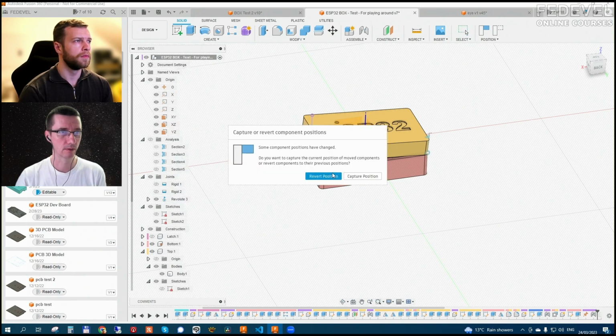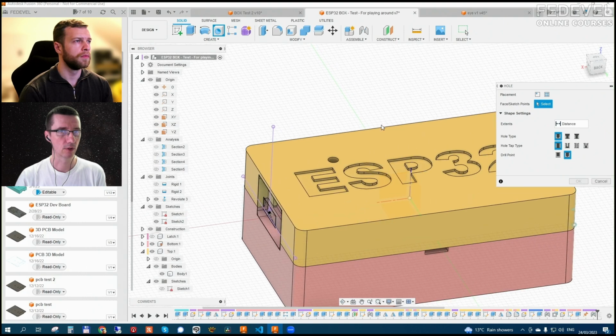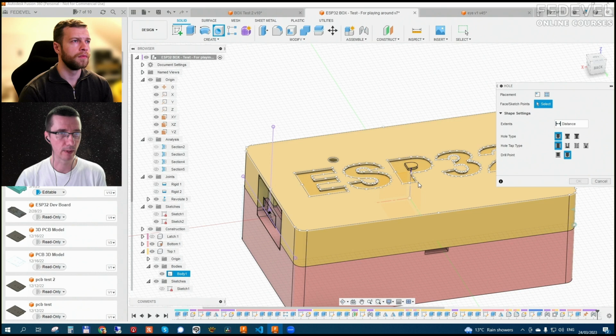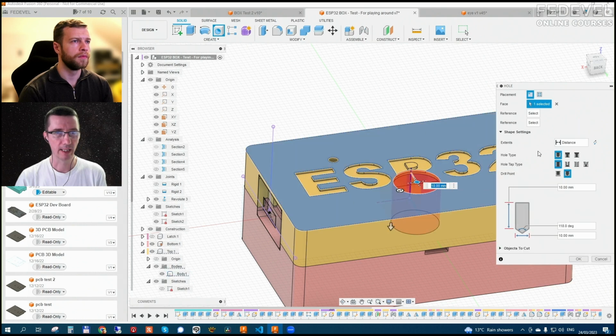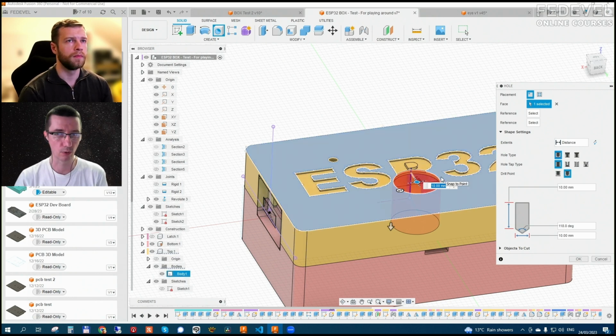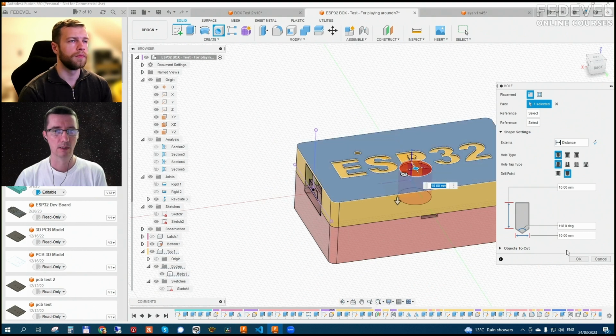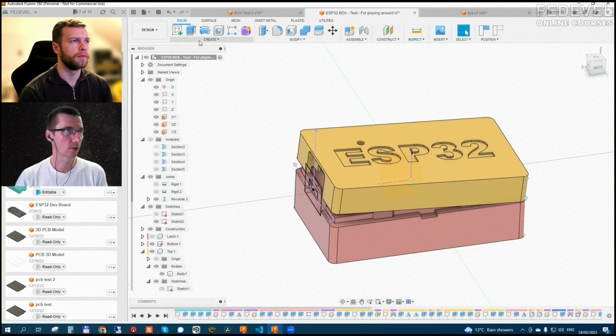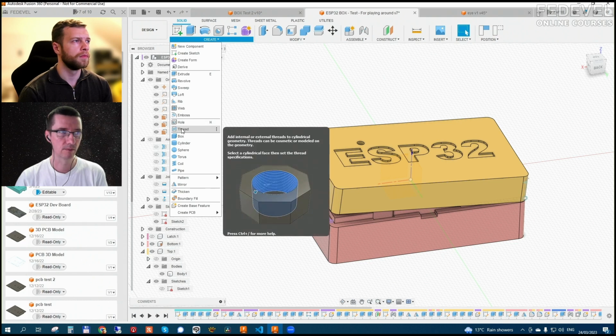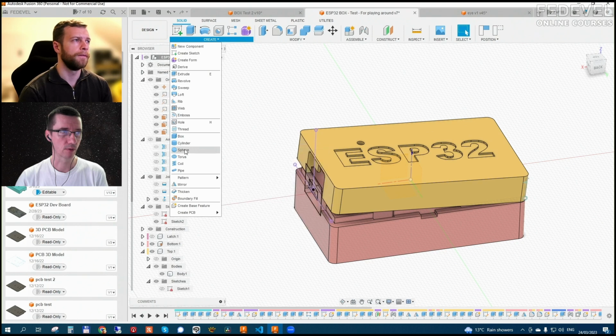I will show you. So I'm going to, let's say, create a hole somewhere. And you can specify what kind of hole you would like to have, and then the depth. This can be useful when you create holes for screws, for example. Then thread, because you can very easily print threads and you can connect pieces together. Cool. I almost never use these.